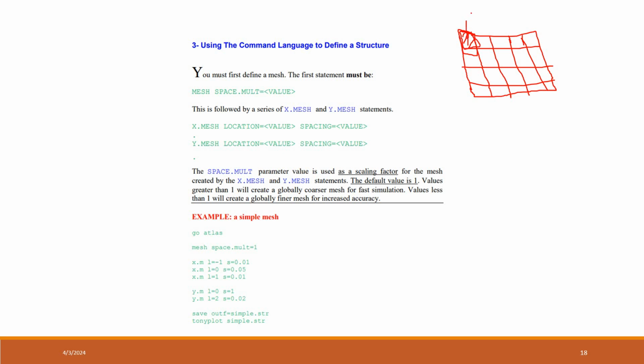It will get the behavior of charge and the movement of charge, everything, for these basic structures. After predicting the electrical behavior of this basic part, our simulator will get the result for the whole device. So if the meshing is very small and narrow, then your prediction will be very accurate. If your meshing is large, then the prediction is not very accurate. So meshing is this.